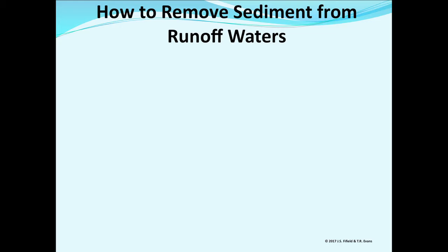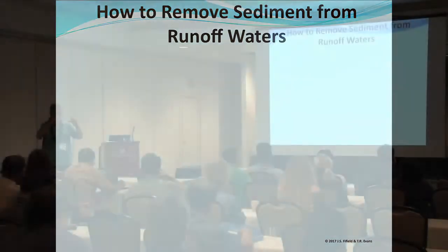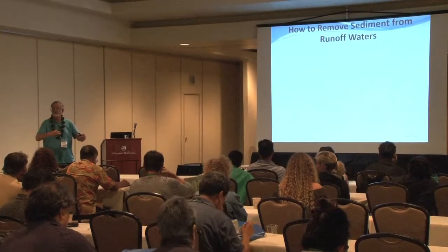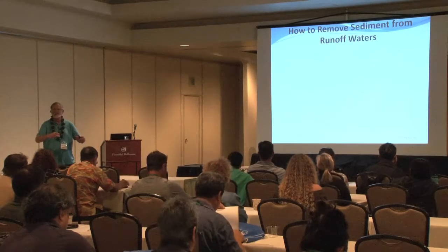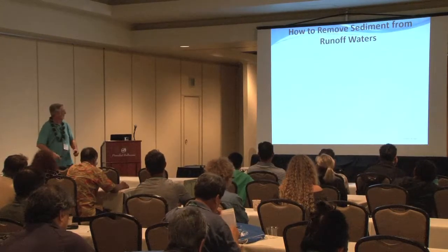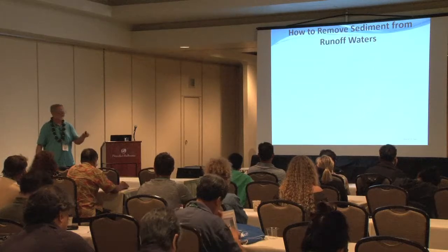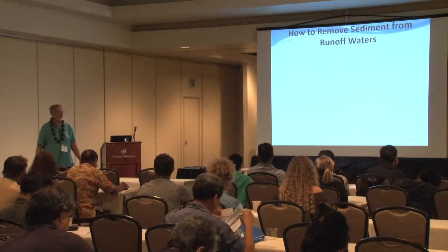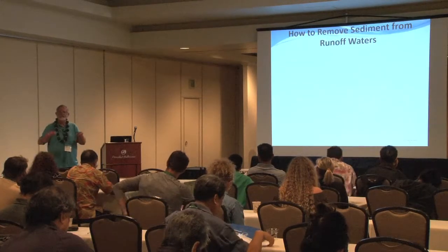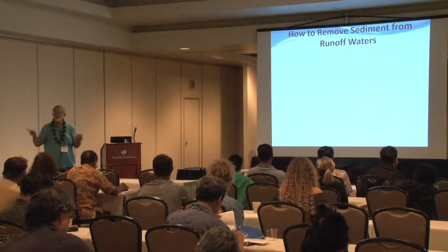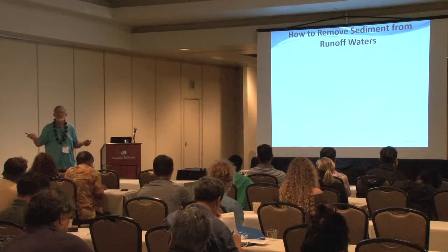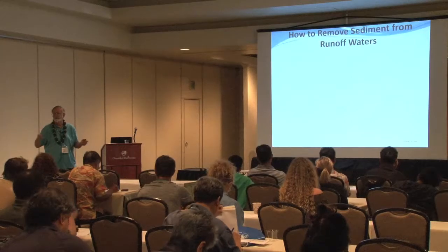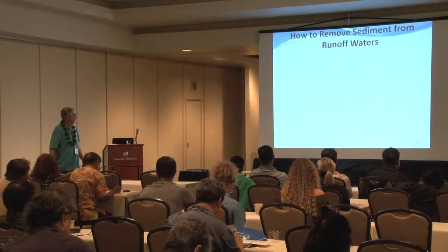And the thing that's important here is don't always think sediment is the material that's deposited in front of an inlet, if you're lucky, or goes into the inlet. But the deposit of solid particles is not the sediment that I'm more interested in. I'm interested in the sediment that's in suspension. When the water during the flood flow events is nice and brown, that's all because of sediment, or predominantly because of sediment.